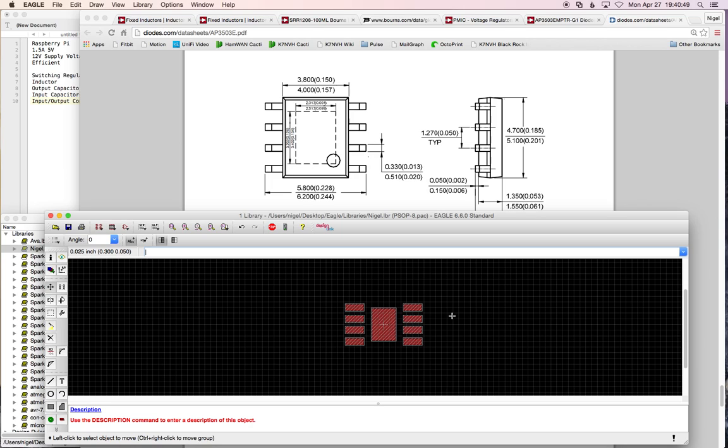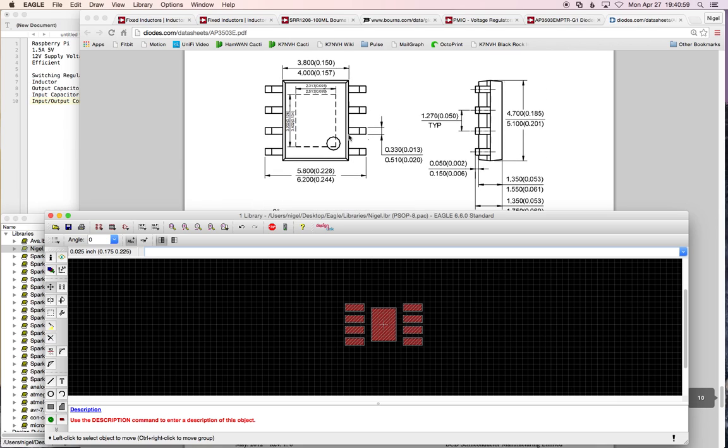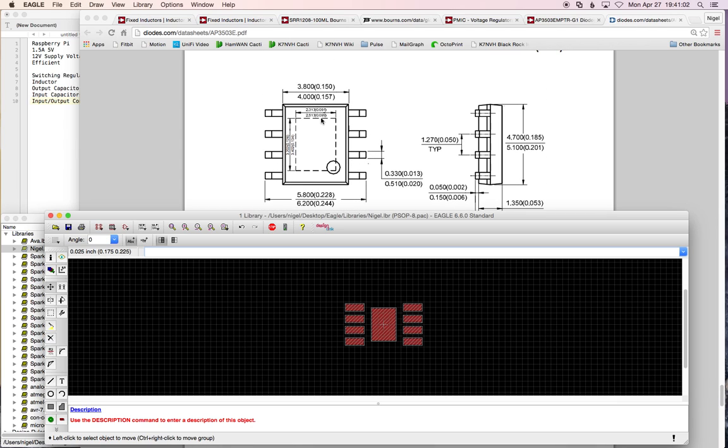And let's see here. So let's take for example these dimensions. We got our 0.1 and our 0.150, we'll call it, is between this width here and this width here. So that gives, in theory, about 50 thou between these added up. So we've got 25 thou on each side. So we got 0.025 I should say, 25 thou per grid division here.